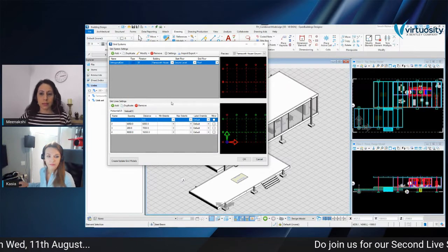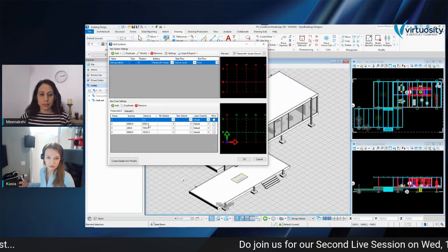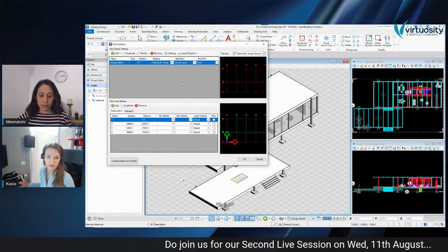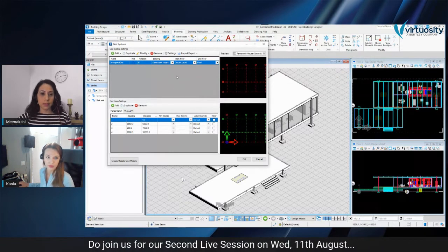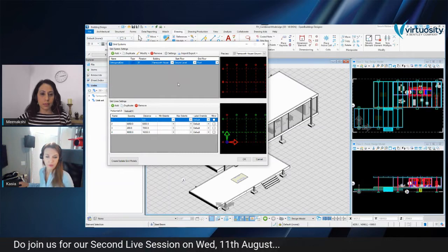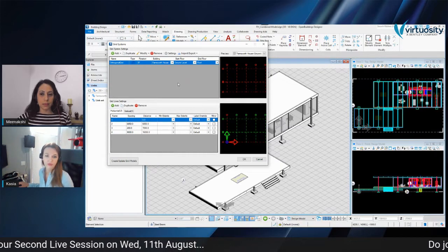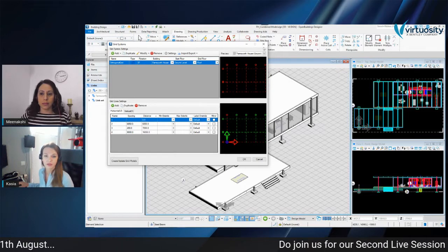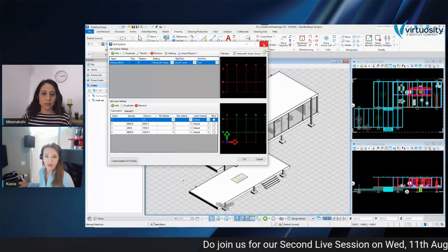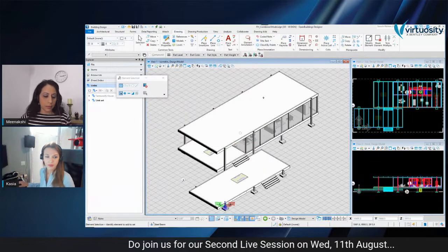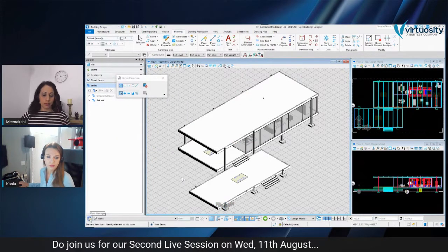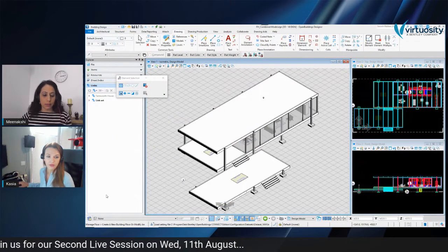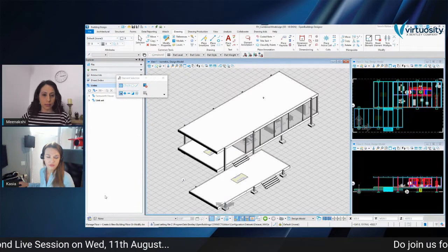And if we modify something, if we set it up for a project, it's the same grid, of course, for every file in our workset. So our project folder containing all the design files, the DGN files, and other project files. So once we have the grid set up, we need to prepare the floor structure for the building.